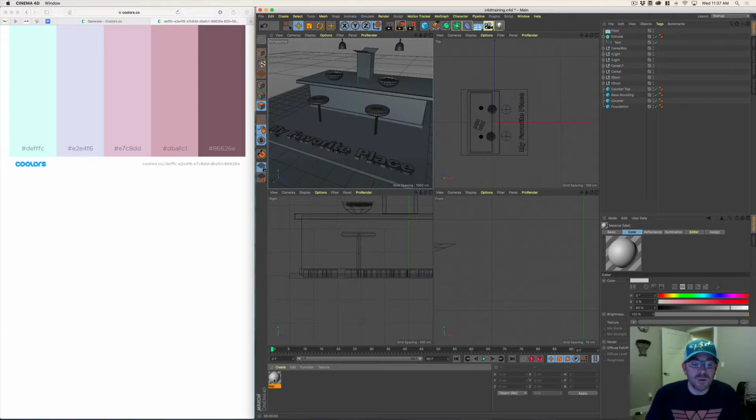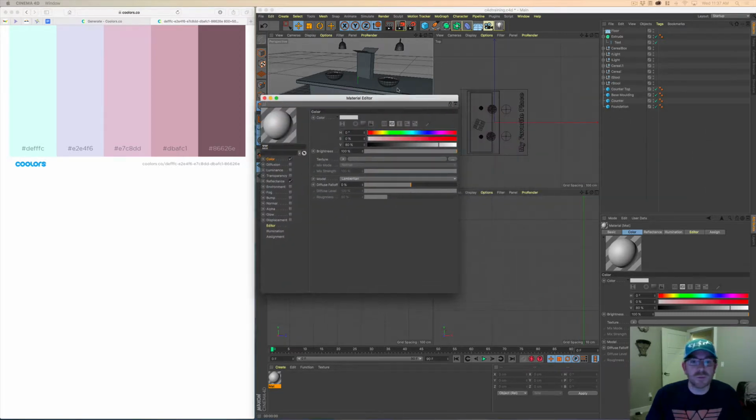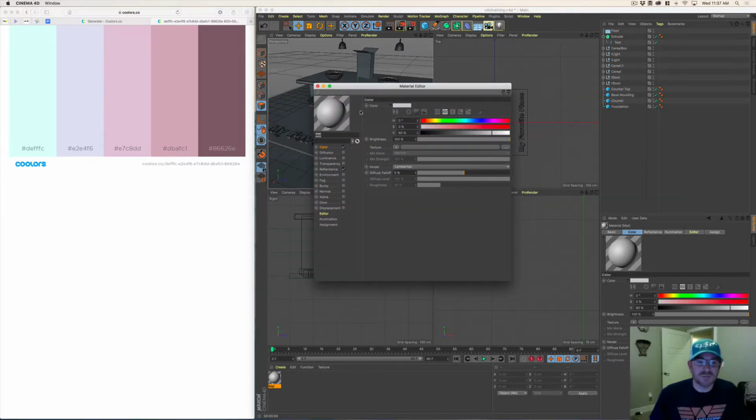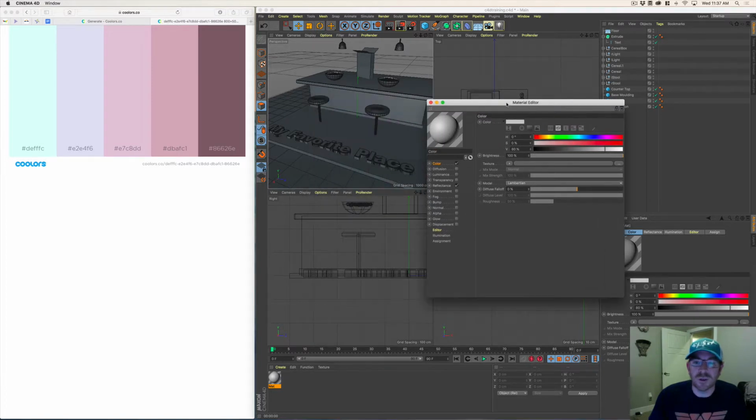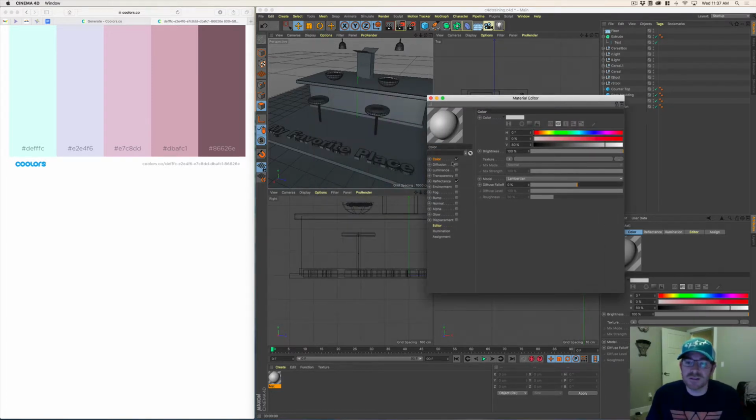So then you double click on this, and the first thing that's popped up in my other window is I want you to name this. Let's call this color 1. Now you may have something specific, like let's call this floor or whatever, but I'm not sure exactly where I'm going to apply this first. Next, there are words here and there are checks here. We want to make sure color is checked and then luminance is checked. Reflectance is by default checked, so uncheck that.